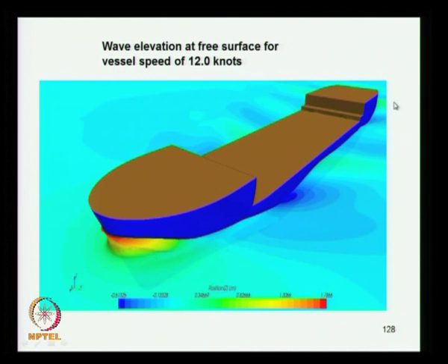This is actually meant for a naval project, which is still in the design stage, so there is scope for correction of the form. As I said before, inclusion of a properly designed bulb is going to bring down the bow wave, and proper fine tuning of the form in the shoulder will also reduce the wave size, and the resistance is expected to come down.